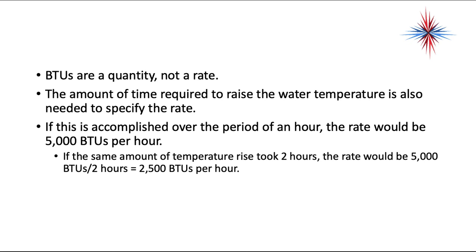Okay, we talked about rates. We talked about feet per minute. I gave you a calculation for airflow coming out of a duct or going through a duct. You take the area of the duct, put it into feet, and then multiply the feet per minute times the area, the square foot of the duct area. Okay, that's a pretty important measurement. That's one you're always going to use.